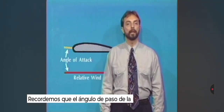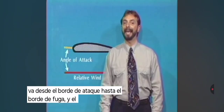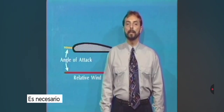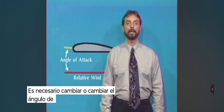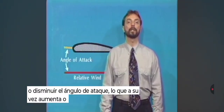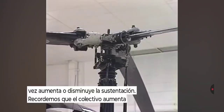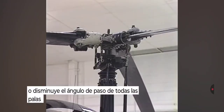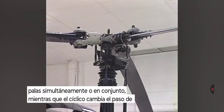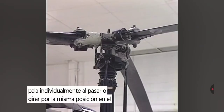Remember that the blade pitch angle is the angle between the blade chord line, running from the leading edge to the trailing edge, and the rotor plane of rotation. It's necessary to change or feather the blade pitch angle in order to increase or decrease the angle of attack, which in turn increases or decreases the lift. Remember that the collective increases or decreases pitch angle on all the blades simultaneously or collectively, while the cyclic changes pitch of each blade individually as it passes or cycles through the same position in the plane of rotation.